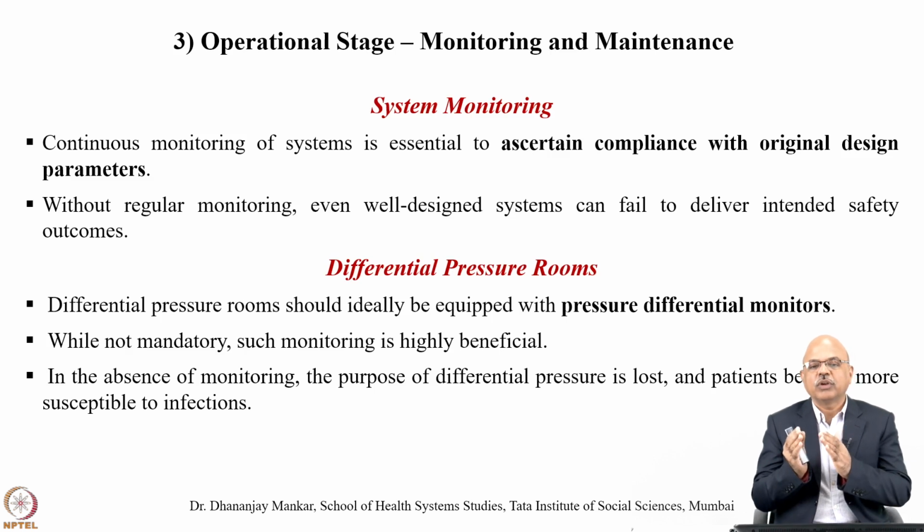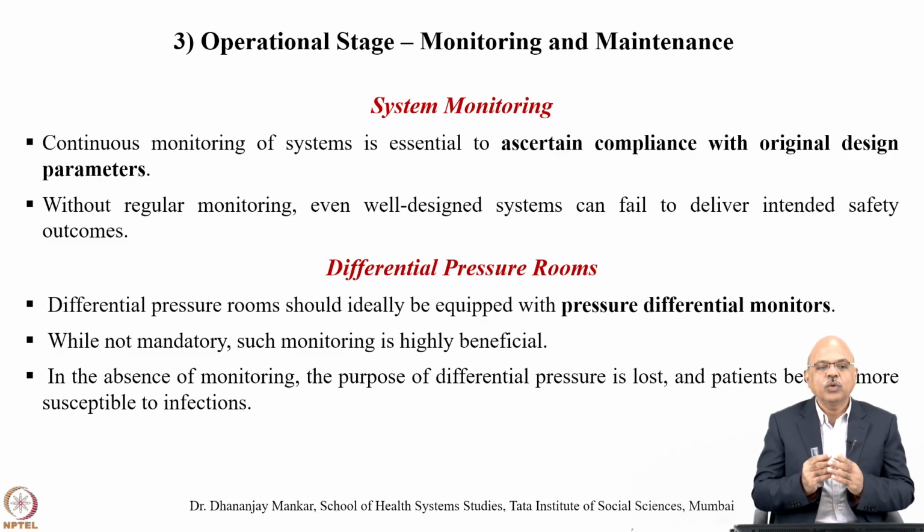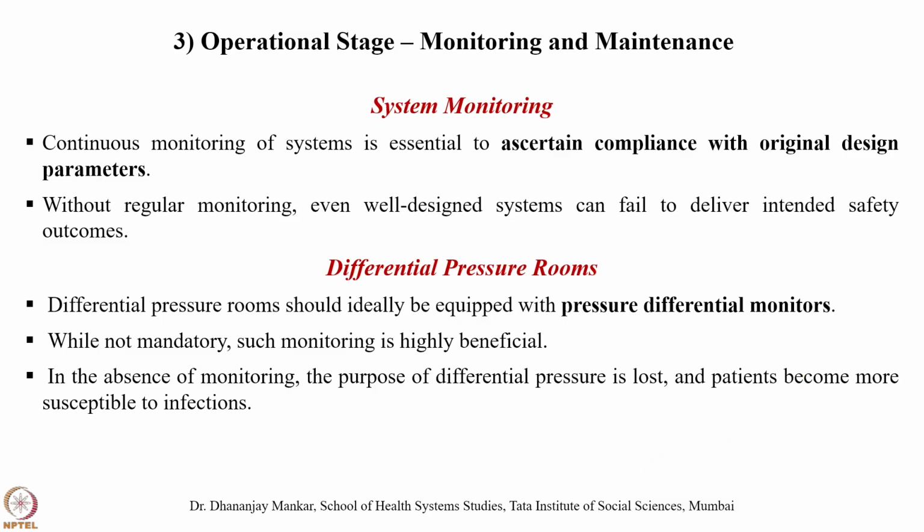Differential pressure rooms should ideally be equipped with pressure differential monitors. Monitoring may not be mandatory, but it is highly beneficial. In the absence of monitoring, the purpose of differential pressure is lost and patients become more susceptible to infections. So monitoring plays a very important role here.